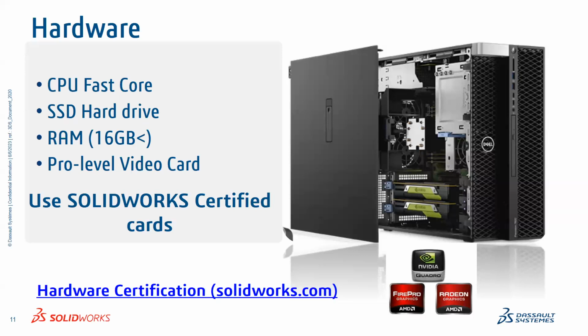So take one average graphics card recommended on our SolidWorks site, which I mentioned over here. It has around 190 million filled triangles per second. It can handle that. So this means it has a limitation. If you are putting in more than 190 million filled triangles, you will feel slowness.